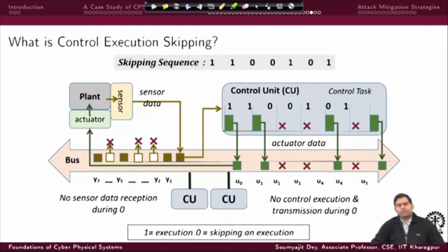That is a nice technique through which attacks can be detected, by deciding that I am not going to send control updates in a regular way. I can either make the controller aperiodic, meaning the controller switches its period and control gain value after pre-decided times, which the attacker does not know. When the attacker continues at the old rate of control, eventually it will be detected.